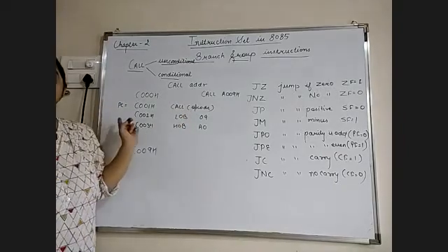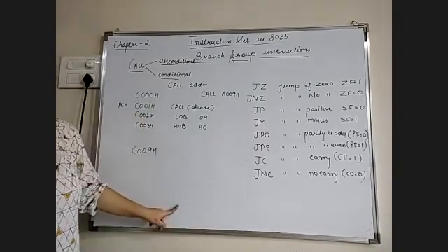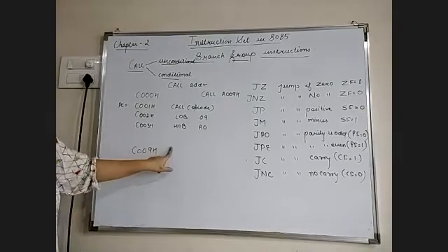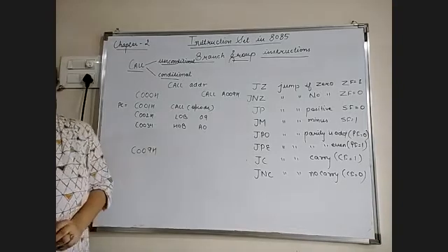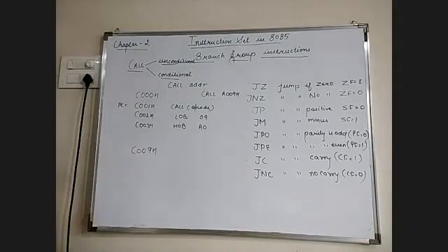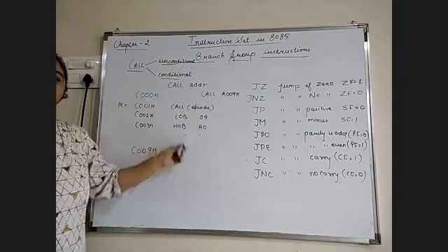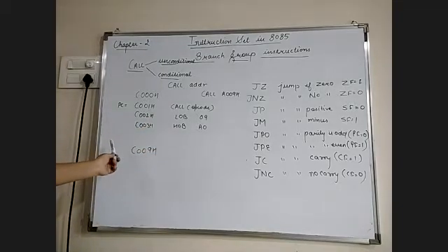Once this instruction is executed, the microprocessor pushes the contents of the program counter into the stack memory. Why? Because after executing the subroutine program, the microprocessor will get back to the main program. From this location the microprocessor jumps to the subroutine program, and after completing it, the microprocessor gets back to the main program. So this is how the call statement works.